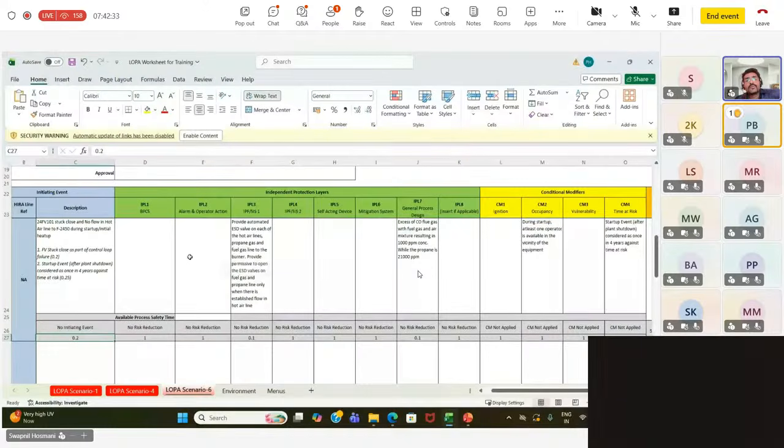Fine, fair enough. But during the HAZOP, this scenario was contemplated because it was a more grave and catastrophic scenario, because there is more flow of fuel gas without any air, and then air is surplus in the downstream system. So there you can get combustion air, and more fuel is passed on to the downstream heater. So it could have been a higher criticality scenario.